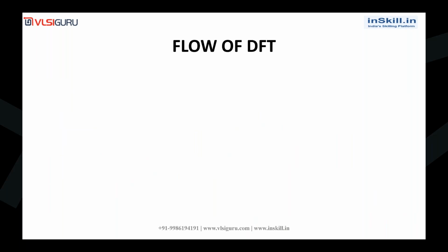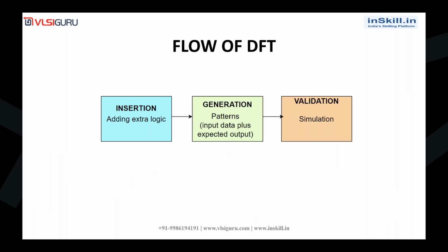And what is the flow of DFT? So flow of DFT means first is insertion. As you know, we will be adding our own test structures into the design, like scan insertion, EDT insertion, boundary scan insertion. Like that, we'll be adding our own test structures in the design.